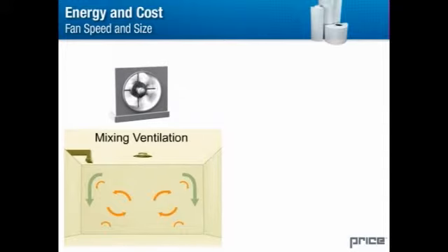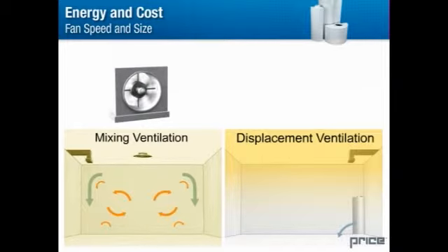For buildings with high ceilings such as factories or gymnasiums, the energy needed to adequately cool a space is extensive. On the other hand, displacement ventilation only delivers fresh air to the lower areas of the room where it's needed. As a result, there are smaller volume requirements placed on the system. In addition to this, the lower pressure and velocity of the supply air coupled with the reduced fan power greatly